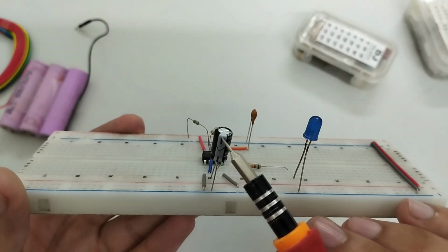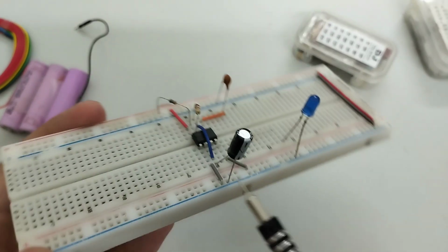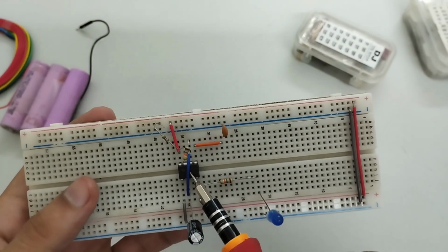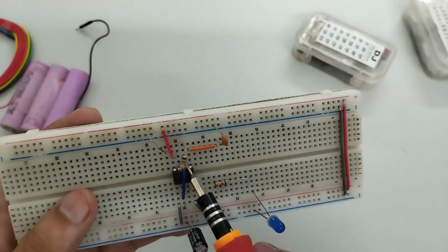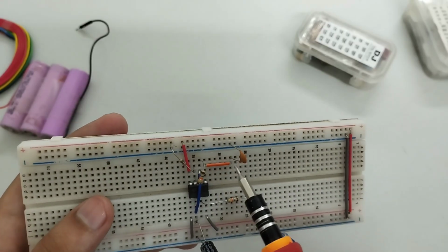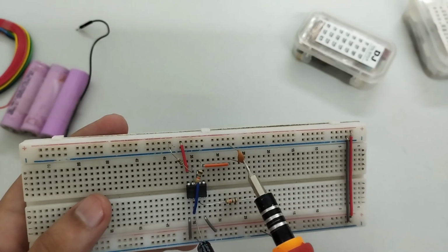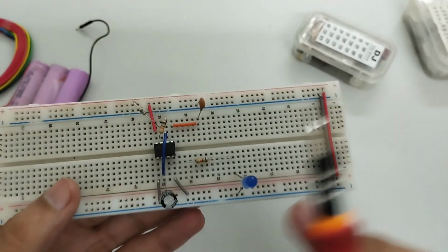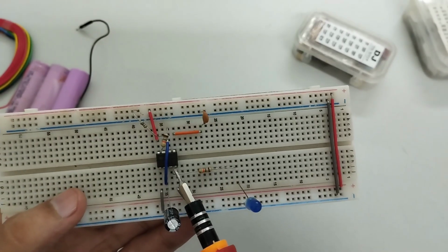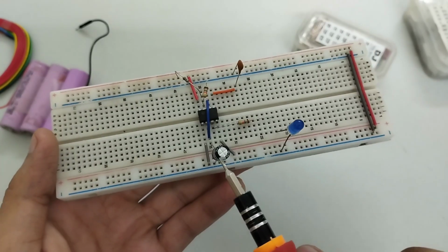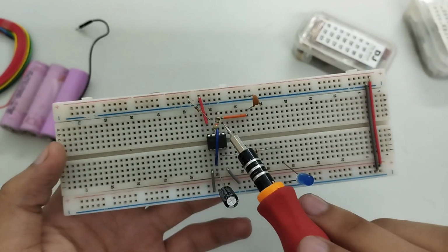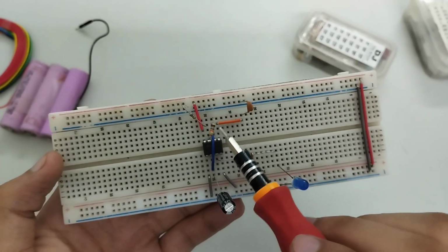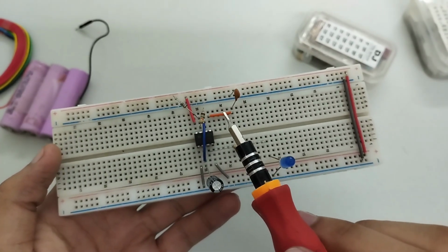So look at this negative sign here on the capacitor. This is representing that this leg is a negative leg. And in 555 IC, if you are not using the control pin, this pin, you can safely connect it to ground using this ceramic capacitor, which is of small value, around 0.1 or 0.01 microfarad. And this is the LED which is connected to the output pin, the pin number 3. And note that when the capacitor starts charging, both of the resistors come into play, right? But when the capacitor discharges, only this resistor, R2, comes into play.